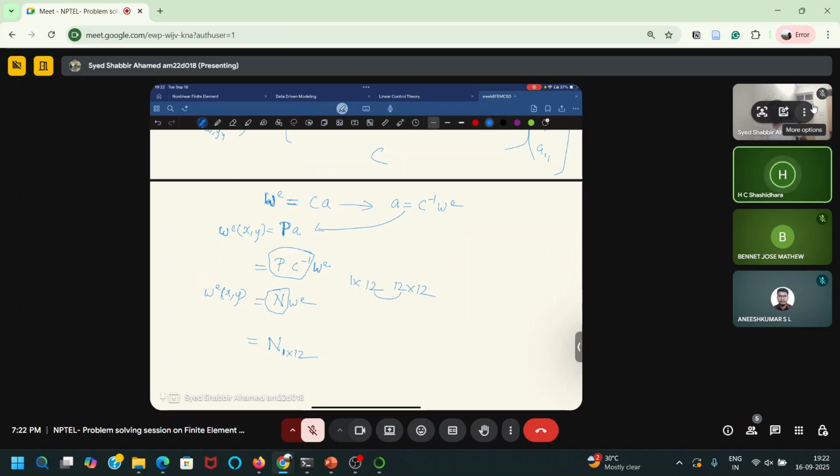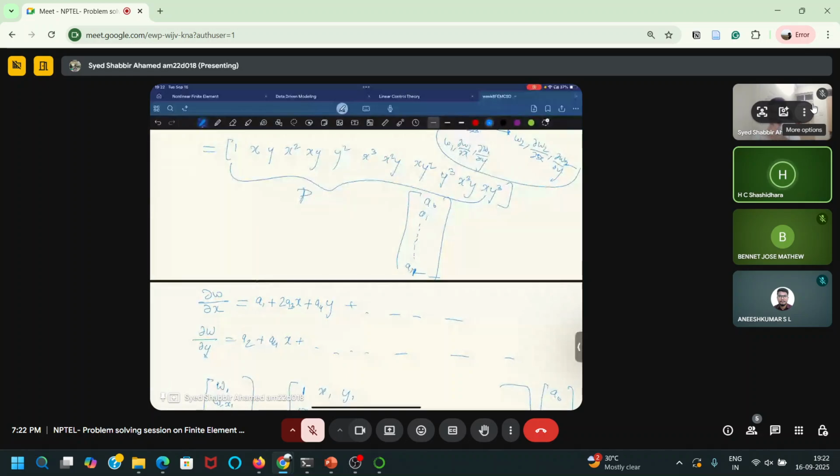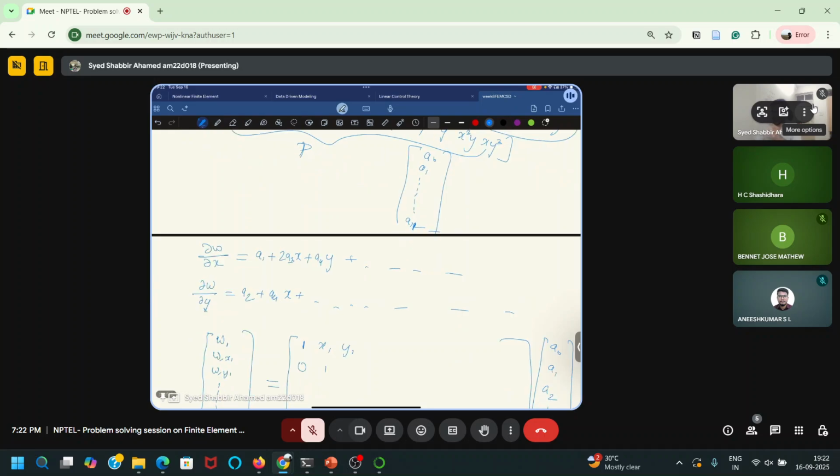I have one doubt. Supposing you want to do this in terms of zeta eta coordinates by using the isoparametric approach, would you get the same answer? Can you take that approach also? Yeah, we also use distorted elements in plates, but that becomes more complex. You have to do the mapping properly. That also can be done.